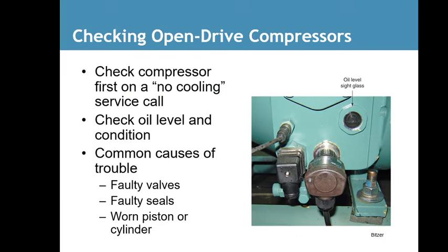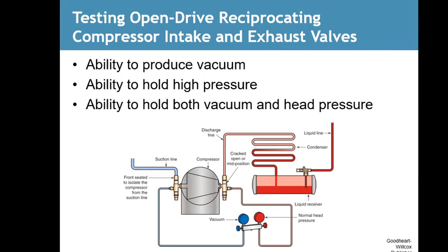Open drive compressor. Check the compressor first on no cooling service calls. So you don't want to go out there and look at the cleanliness of coils or check contactors until you know the compressor is fine. Check the oil level and the oil condition. Common causes of trouble: faulty valves, faulty seals, worn pistons and cylinders. Testing an open drive reciprocating compressor intake and exhaust valves. It needs to have the ability to produce a vacuum, ability to hold high pressure, and ability to hold both vacuum and head pressure.